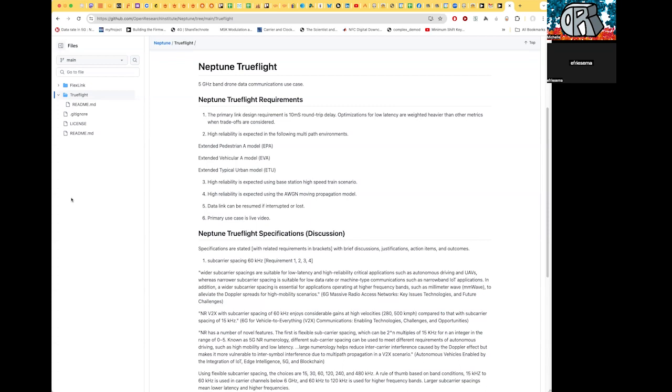Yeah. So I think that requirement number one needs some definitions. The round trip delay to me was RF delay. 10 milliseconds was pretty generous, but I thought it was definitely beating the 20 to 40 millisecond round trip delay that I was quoted. But we're talking about two different things. To me the 10 millisecond round trip delay is the RF delay, and the 20 to 40 is glass to glass. And I'm like, oh, okay, these are two different things. And then the feedback that the RF needs to be lowered to 4 milliseconds or lower was really good feedback.